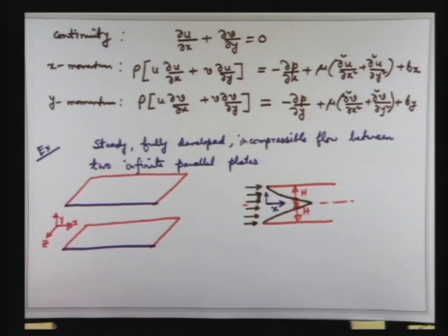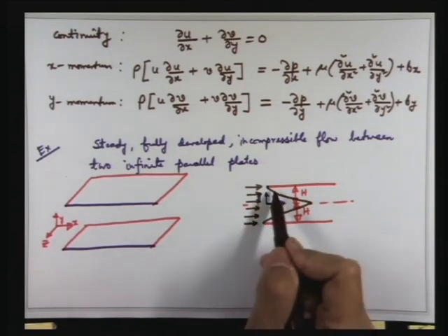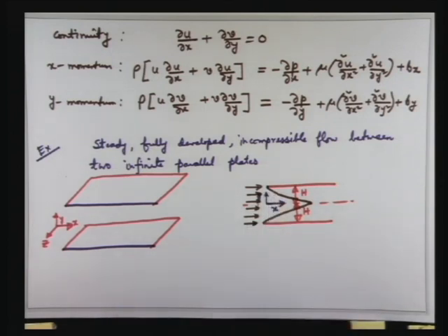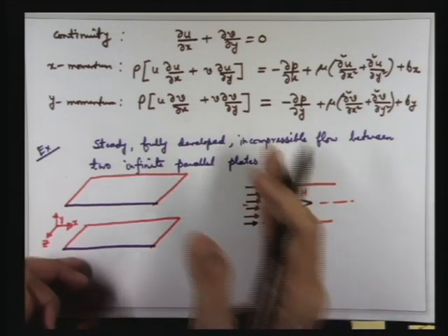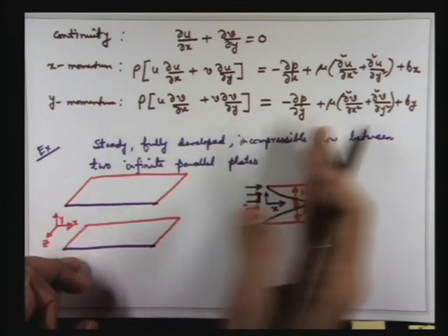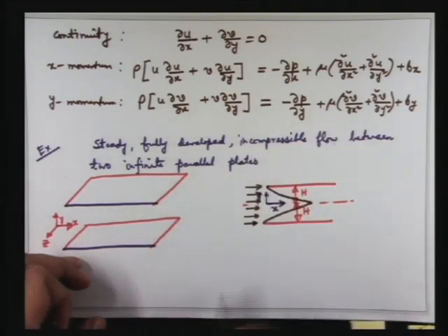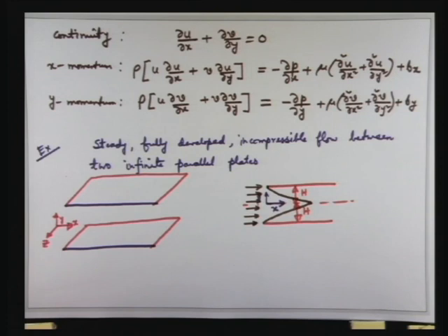So please think about it in your leisure time: how the velocity profile, the pressure profile and the wall shear stress profile change as you are traversing across this developing region. The developing region or entrance region is the region in which these boundary layers are growing.